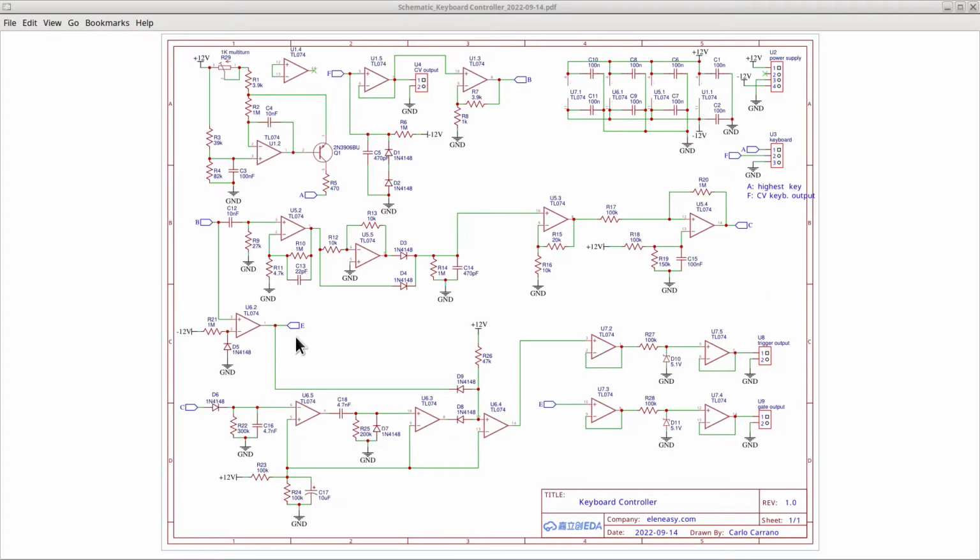However, the voltages are not a TTL level as they should be per our own requirements. To make them compliant, we now need to remove the negative part and have in its place a 0 volt. In addition, we need to cap the voltage output to plus 5 volts. Op-amp U7.3, along with R28 and the Zener D11, do just that. Whenever the voltage is positive, the Zener will cap it at 5.1 volts.